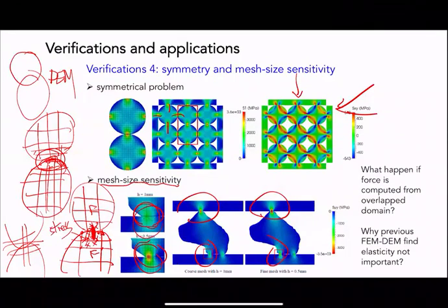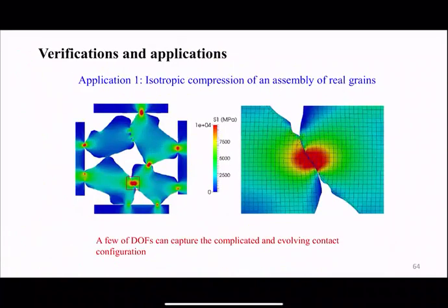As you can see here, it probably doesn't matter how coarse the mesh is unless it's super coarse. But you can see that the mesh quality, or the number of Gauss points or stress points, is a resolution issue that needs to be tackled before we can actually resolve the stress field properly. So this is one problem.